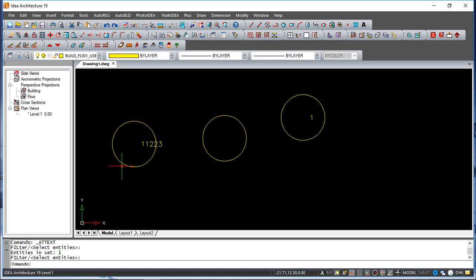Then you have the last group of functions, what we can call the external references. And with these external references, we can link separate information entities to a drawing. And this is also a very useful command, because one of the main ideas that we can give about the use of these external references is the possibility that we have to link an outside drawing to our current one.